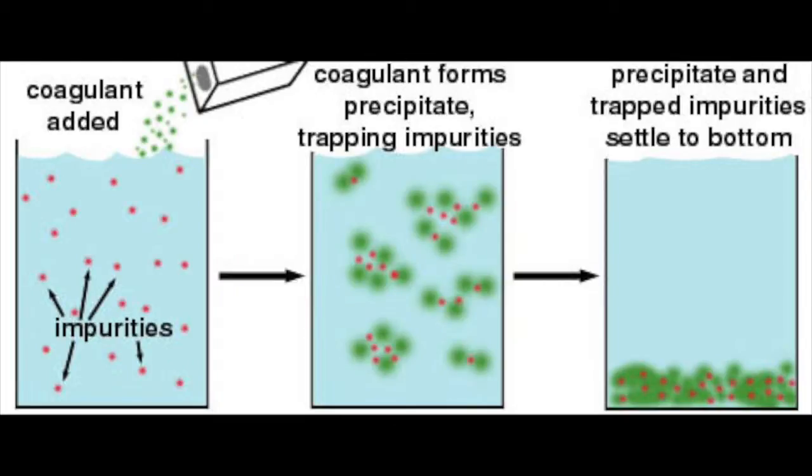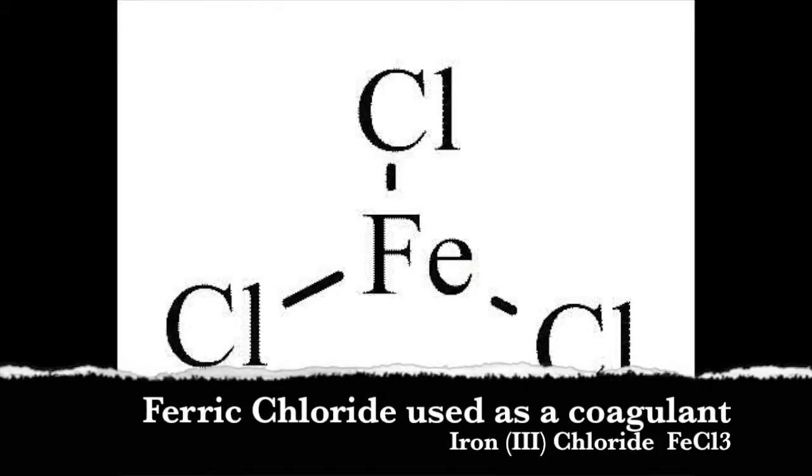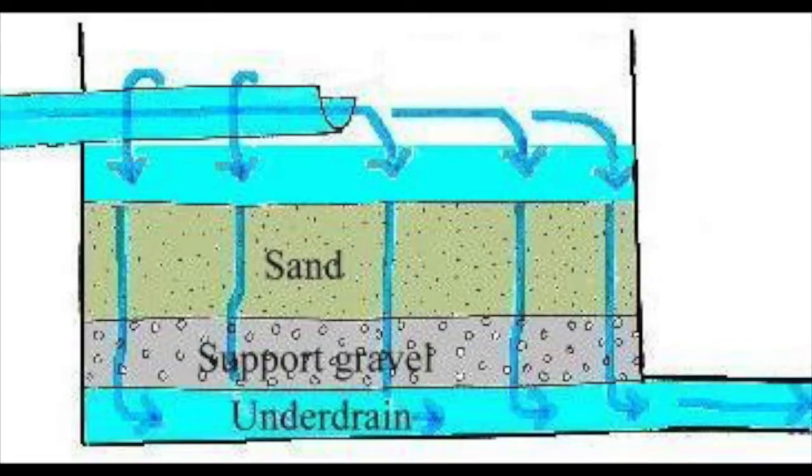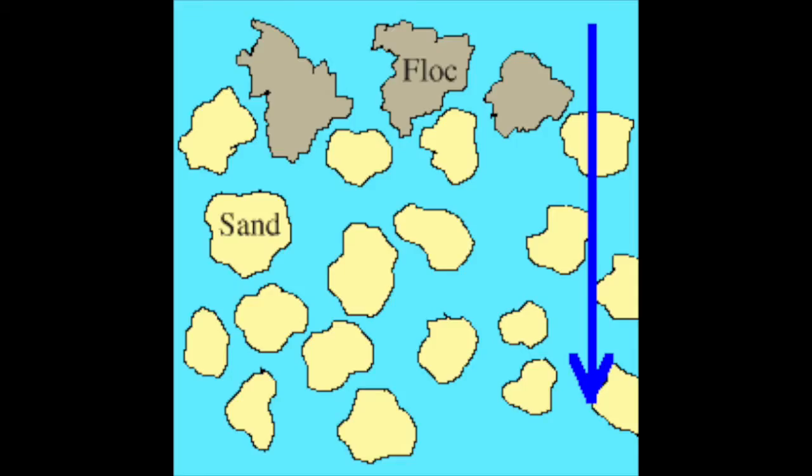This step aims to achieve filtration on large levels so as to make flocculation easier. Flocculation. Chemicals are added so that the remaining particles join together into larger masses, called floc. The main coagulant used is ferric chloride. Small amounts of polyelectrolyte, a long chain of polymers, are also used as a secondary coagulant. This aids the filtering process. The water passes through filters that include either sand or layers of sand and anthracite, crushed coal. These filters trap the floc and separate it from the filtered water. This is used to get rid of much smaller contaminants on a larger level than filtration can achieve.